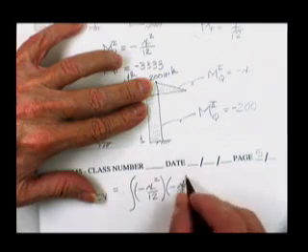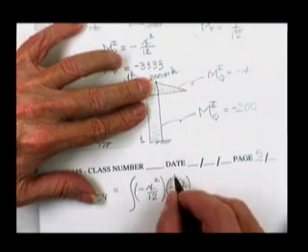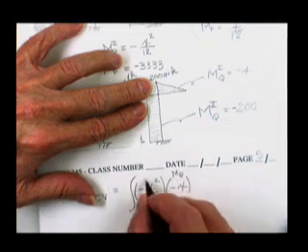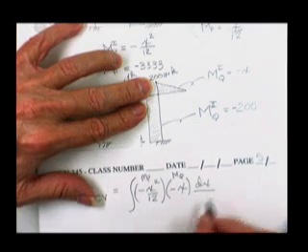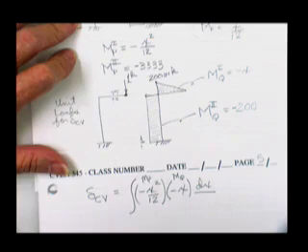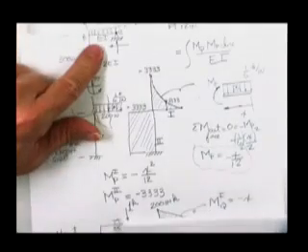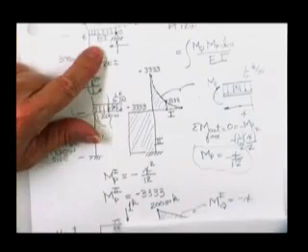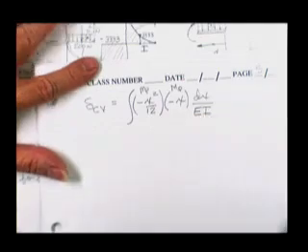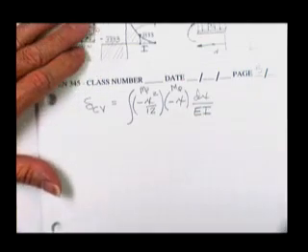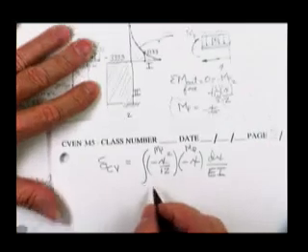That's reversed from what we have in the book. This one is the m sub q, and this one is the m sub p, times dx over, and I'm going to now divide by our real EI. According to the boss, our EI for this piece is really EI. So I'm going to change EI generic to EI for our beam. And that should be integrated. It should start at x equals 0, and it ought to end up at 200.